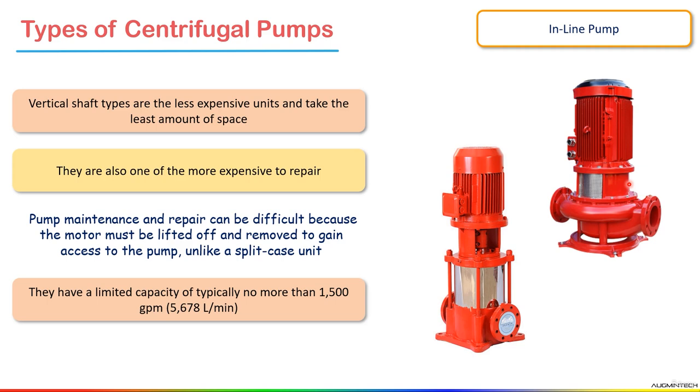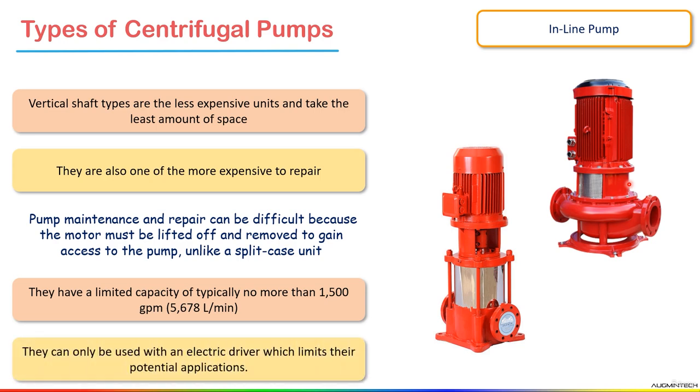We have a horizontal split case pump, but what is the limitation of using that pump? The space requirement for a horizontal split case pump is the highest compared to other pumps. Now, they can only be used with an electric driver, which limits their potential application. So this is all about inline pump in firefighting.